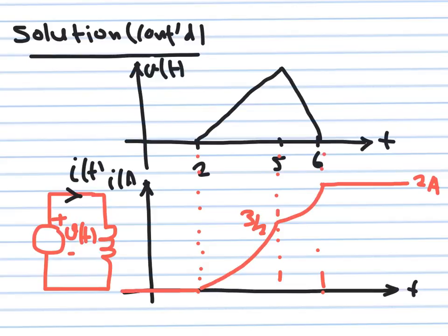Why is that? Simply because it is stored in the magnetic field of the inductor. It is the same current going through the loop, and there is nothing that would stop it from continuing to flow, even though the voltage reaches 0. And this is something you will know, and it was mentioned in one of the slides: if you have DC, then the inductor looks like a short circuit, but still a current goes through it, and it's accumulating magnetic energy. It's very important to remember that.